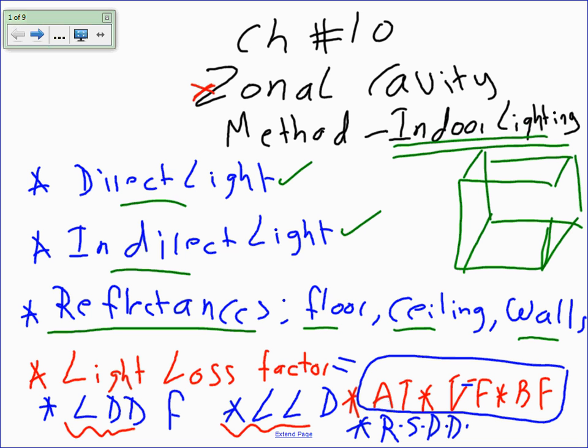The second thing is also for lighting fixture, there's called light loss factor. You guys were assigning a 0.82 for the fixtures that we use in Lithuania for the luminaire fixture indoor. That's based on experience. That 0.82 is a good light loss factor. When they do the light loss factor, they take into consideration light depreciation factor, lumen depreciation factor. There's a bunch of other factors that they take into consideration.